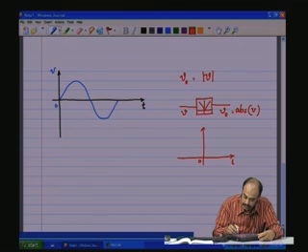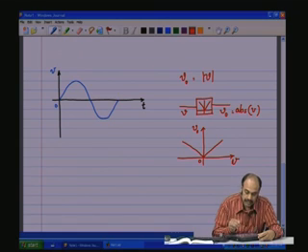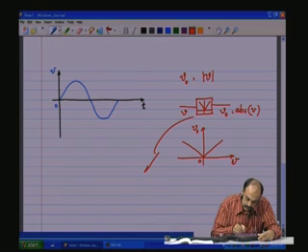Sorry, this is in terms of the input, this is V and this is V naught. So, whatever be V naught is positive, which means if you have V positive, V naught is positive. If V is negative, V naught is still positive. So, that is what this graph represents. This is an absolute value circuit. A full wave rectifier is an absolute value circuit.